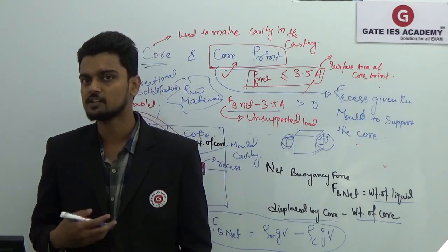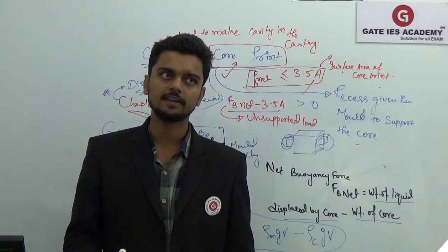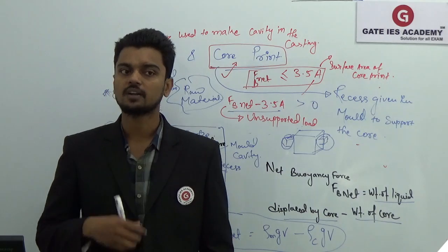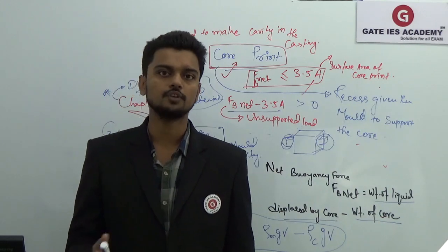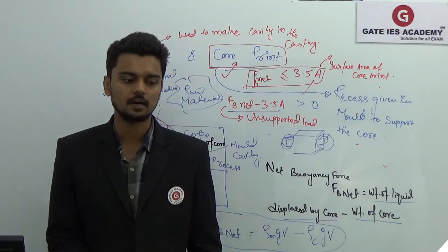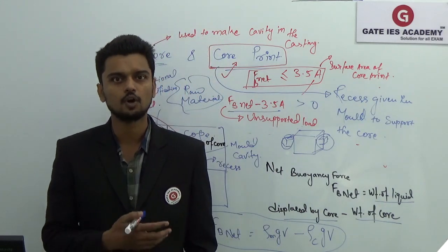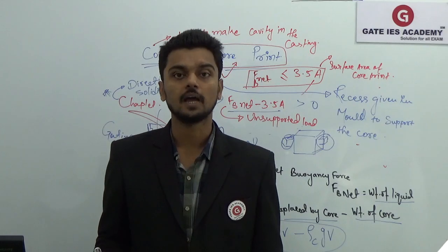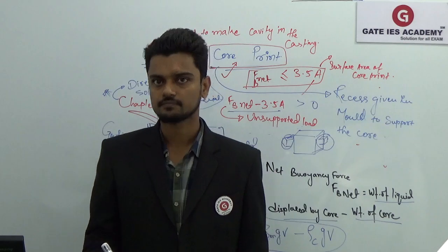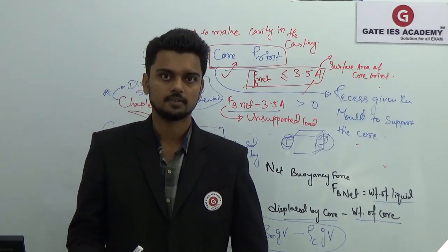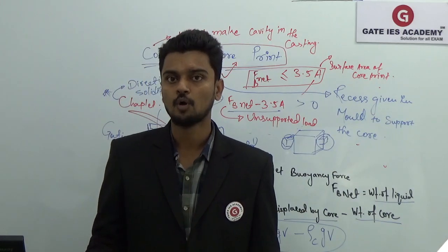As I said, its material should be the same as your casting material, so that the heat present in your molten metal will try to melt the chaplet, and it becomes a part of your casting. But practically that is not true, because the heat will not completely melt your chaplet. Also the chaplet should be clean from moisture to avoid defects.